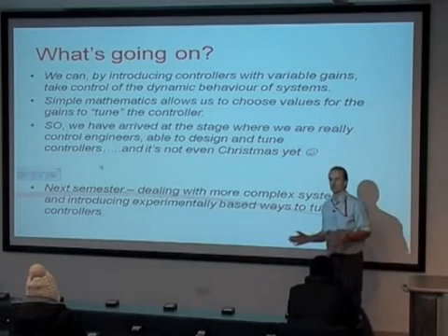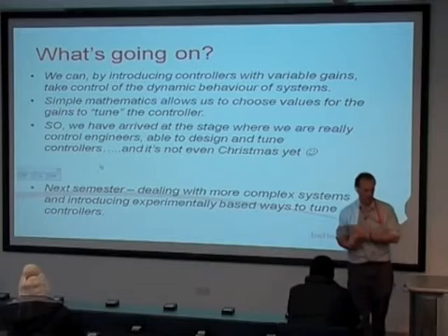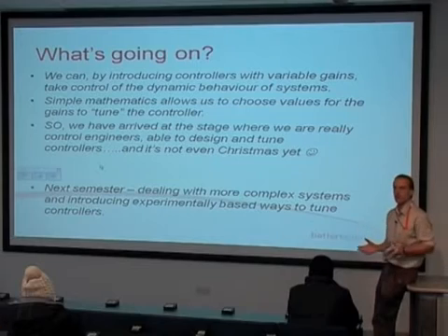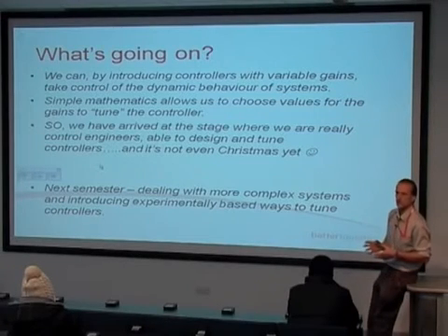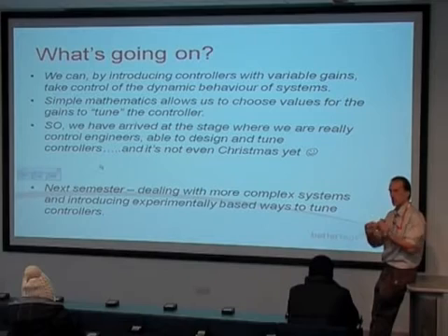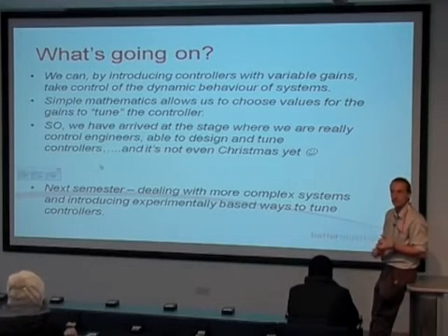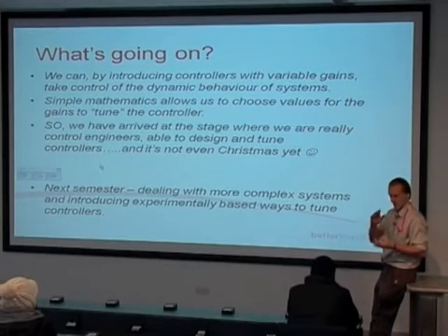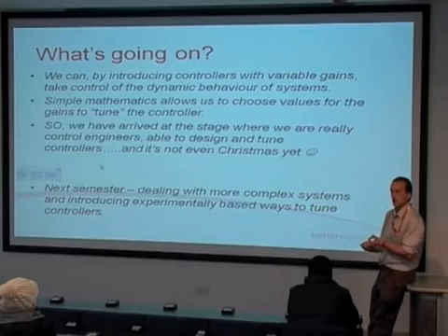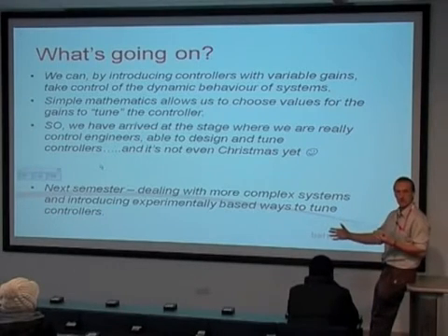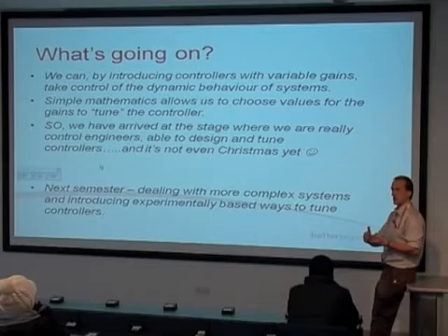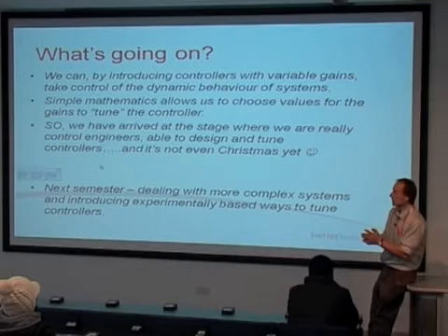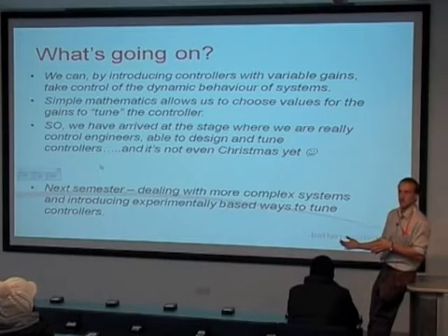So what's been going on? Well, what's going on is we can introduce various standard configurations of controller. I've shown you a straightforward proportional controller, a 2-term controller, which introduces the integral term, a 3-term PID controller that introduces the differential term, and a modified PID, which is the IPD, same 3 terms but in a different configuration, which is algebraically a lot more convenient.